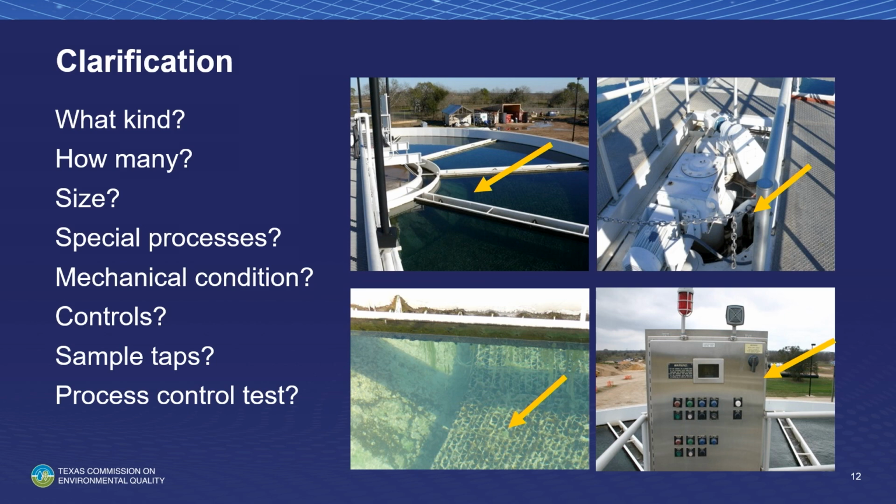Back when I started in the 70s, we actually had investigators that were working for the health department. Tony will verify this. They would walk up on site, and if the clarifier was round, it was a solids contact upflow clarifier, okay? And it was a matter of training and experience and time. Not all clarifiers that are round are solids contact upflow clarifiers. Some of them may be just a center-loaded cross-flow radial clarifier, you know? That happens. Not all solids contact upflow clarifiers are round. There are some that are square.